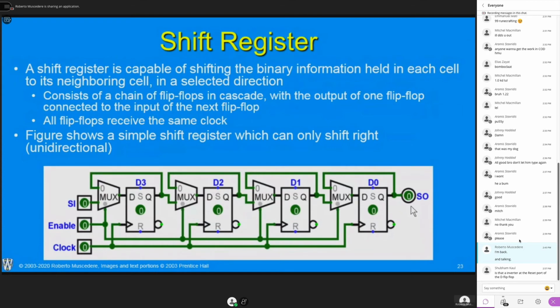Now, do keep in mind that the clock rates at which we send data serially in the technology we use are very high. So you'd say, well, why didn't we do this earlier on? We just couldn't generate clock rates that way, and we didn't have the ability to do wiring as well as we can now, to lower noise wiring and those particular things. So a lot of earlier technology used parallel transfers, but over great distances, that has a problem. So a lot of the technology in your computer today is serial.